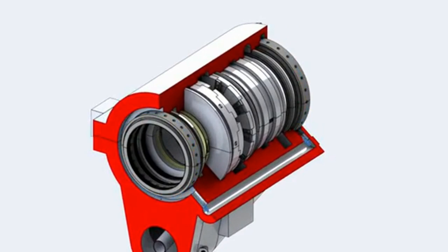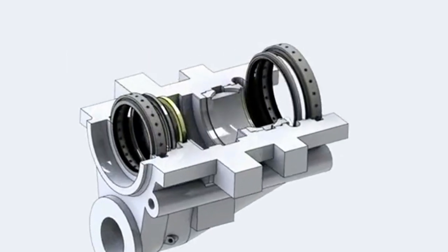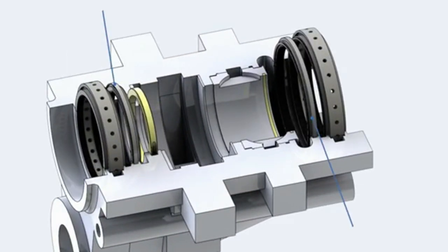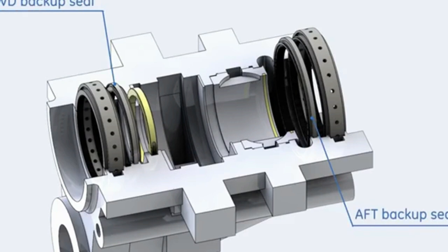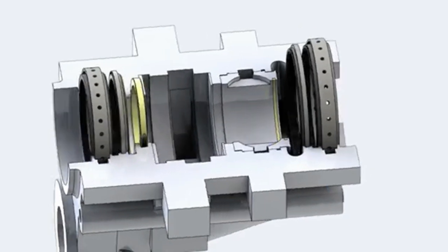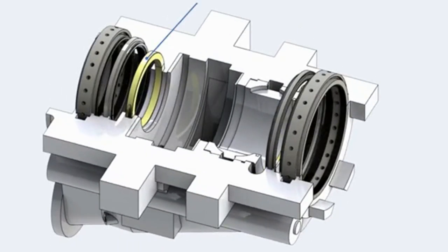Between the two rows of seal teeth, sealing air is admitted through multiple radial holes to stop oil from spreading along the shaft. Some of this air returns with the lube oil and is vented through the lube oil mist eliminator, and some escapes out of the housing. Inboard of the main pressurized seals, two backup labyrinth seals are installed for positive sealing. A floating seal is installed on the forward of the thrust bearing cavity to contain the oil.